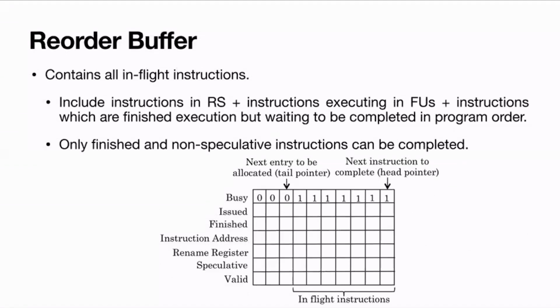So all the instructions just before that particular exception creating instruction, we just complete the execution and save the state, and then handle the exception and then come back to this third instruction and again execute the remaining things. So the difference between exception and interrupt is, interrupt means all the in-flight instructions are going to be executed and then handle the interrupt service routine.